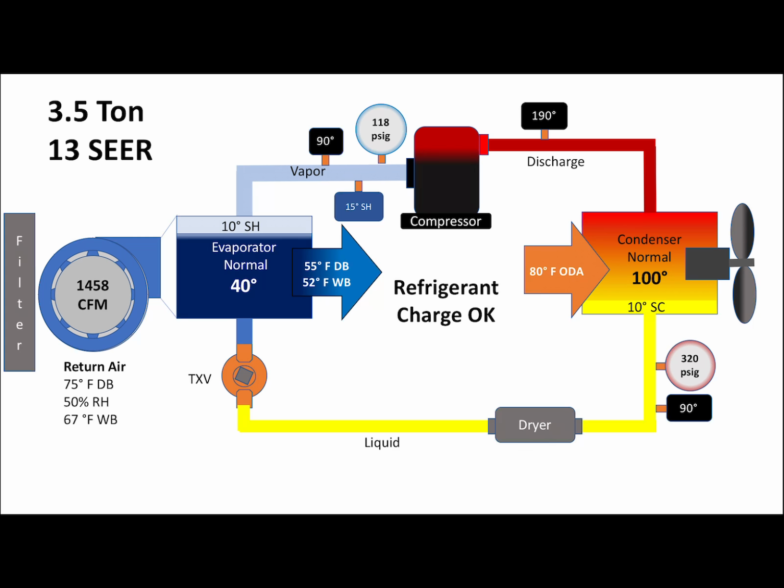So we're evaluating this. measureQuick's looking at it from a whole system approach. And it's really important to understand we're going to record what are called design temperature differences, or condensing temp over ambient. It's how much colder is the evaporator than the return air, and how much hotter is the condenser than the outdoor air, right? And those are two variables that are going to really dictate the efficiency of the equipment and also the rate of heat transfer.